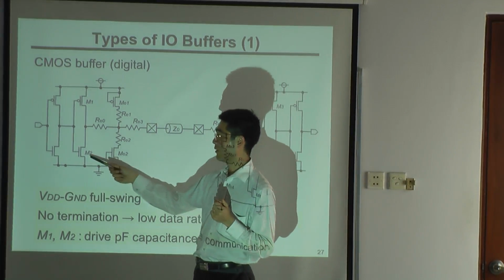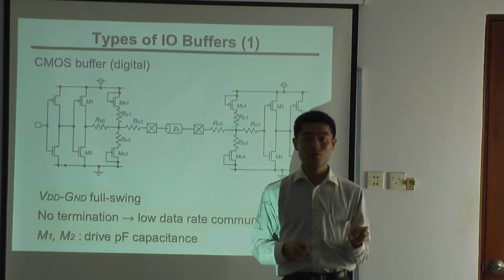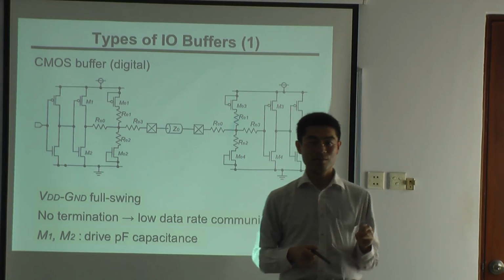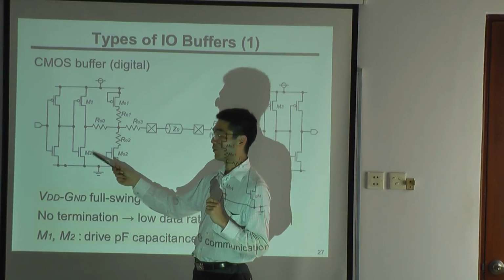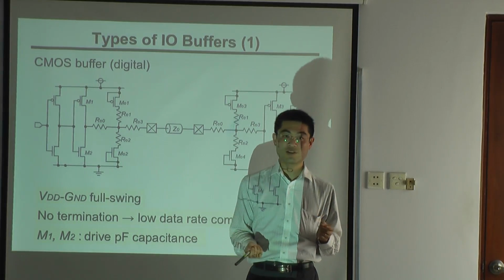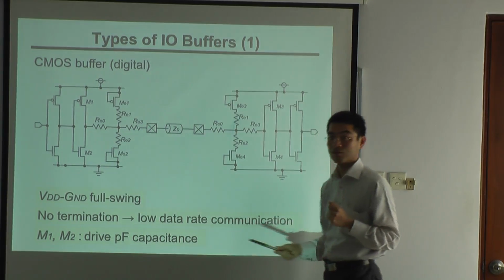So it is about 100 times larger than the transistors used inside the device. So you may use transistors 100 or more times larger for I/O buffers in order to drive off-chip devices.